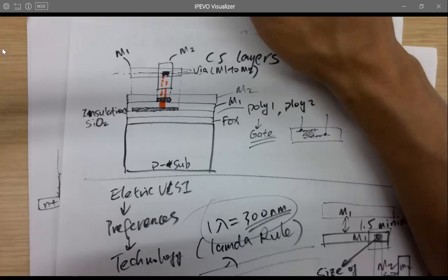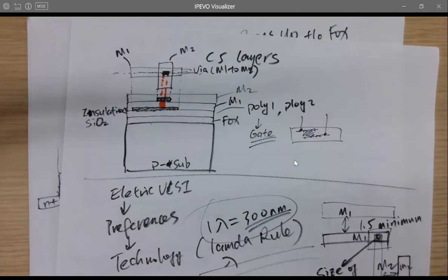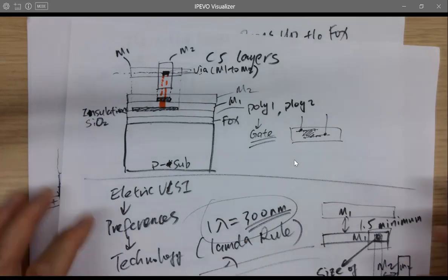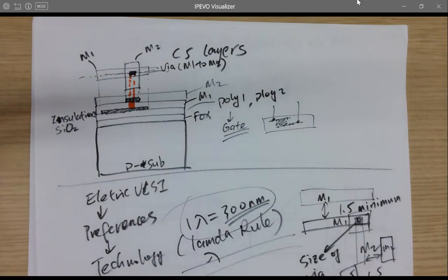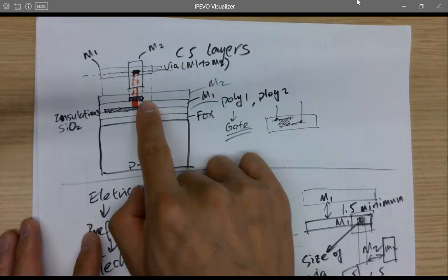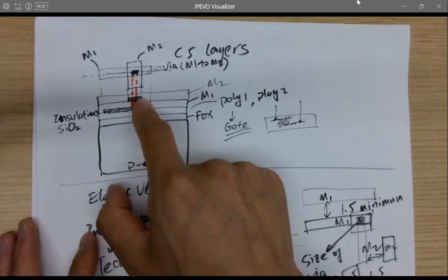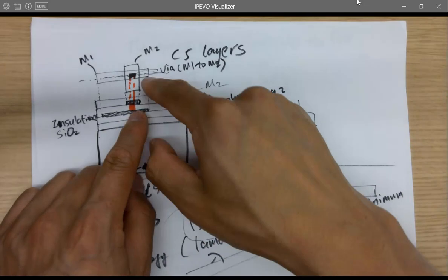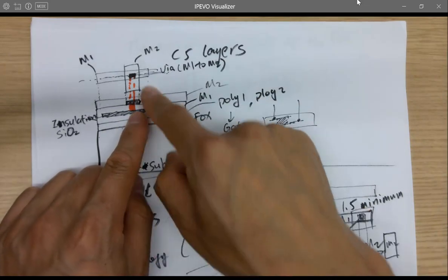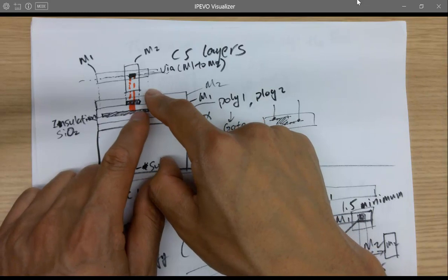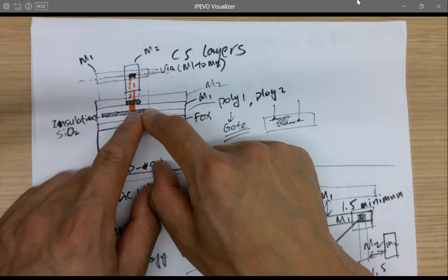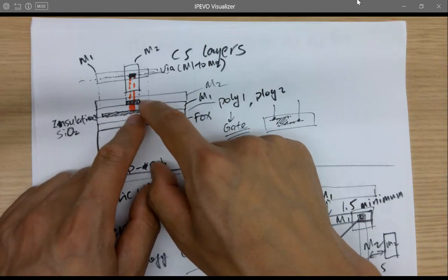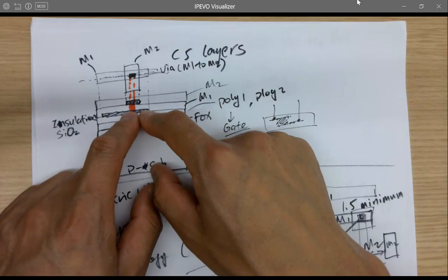But you know, the reason that I know the via or the contact is a little contact between poly and metal 1, and I know that's metal 1, the gray color looks different from the blue colors, but I know it's metal 1 because from the layers, you know on top of poly is going to be metal 1. It doesn't make sense you have a poly and the contact is drilling the holes through 2 layers and connect to metal 2. You know what I mean? And you don't want to just keep the poly in there without any contact, because you do need a signal to get into the poly or get out from the poly, right?